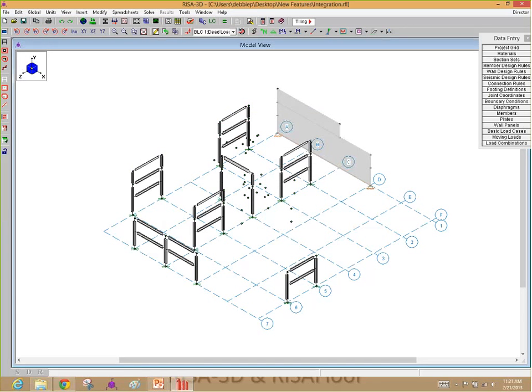And what I see, which is really nice and brand new, is that we actually can carry those virtual joist girders at the top over to RISA 3D, which is a new thing because previously they would have been working off of tables, and would not have been able to carry over to RISA 3D. But now we can actually count on them as part of our lateral system. Now, I don't know how often people do that, but we have had several requests for that, so it's a nice thing that you can actually take that virtual joist girder right over into RISA 3D for lateral design.